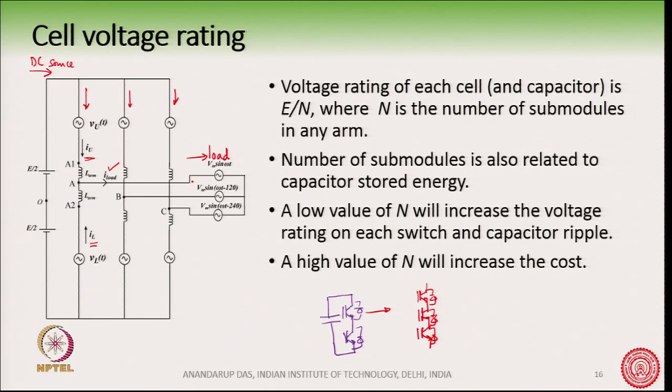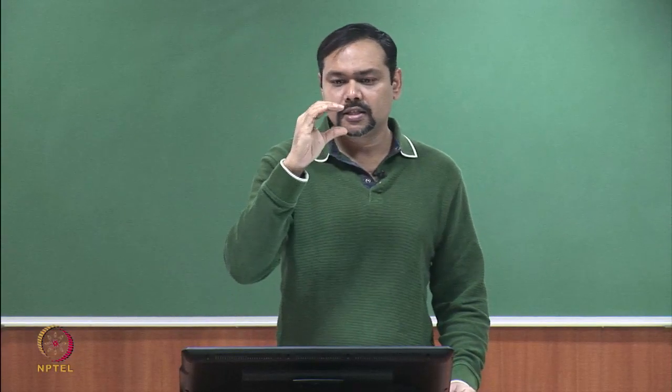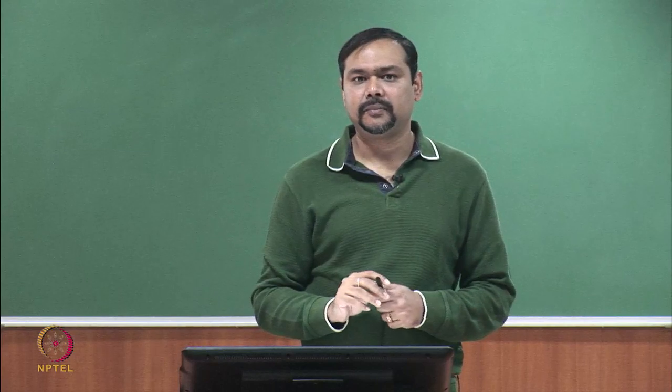Why are these arms needed? Because they are creating this multi-level sinusoidal voltage source. They are very much needed, and it is important for us to keep the capacitor voltages at a fixed value. If the capacitor voltages are going up or going down, then we will not so easily get the sine wave output, right. If the capacitor voltages are diverging, we will have a non-sinusoidal output. We have seen this earlier also, that if the capacitor voltages are not kept at a particular value.